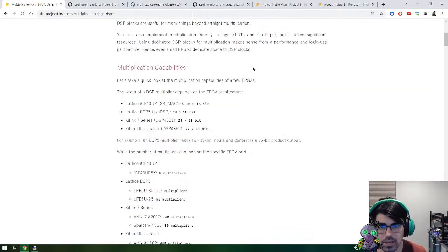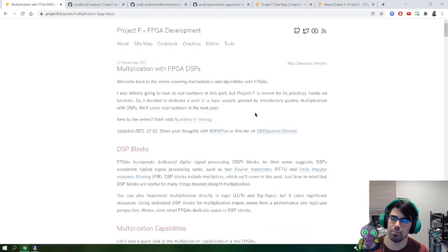This seems like a good website to become more familiar with what FPGAs are capable of. Besides the HDL, a good FPGA designer is going to know the primitives that are on the FPGA. We're going to know if we have a LUT4 or LUT6. We're going to know the different flip-flops, the SRLs, the shift registers.